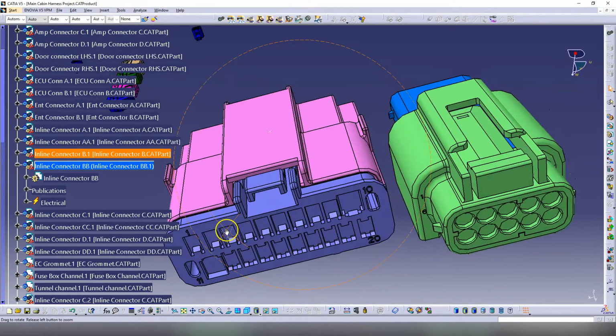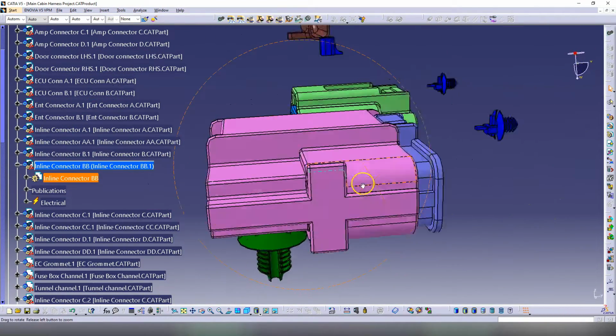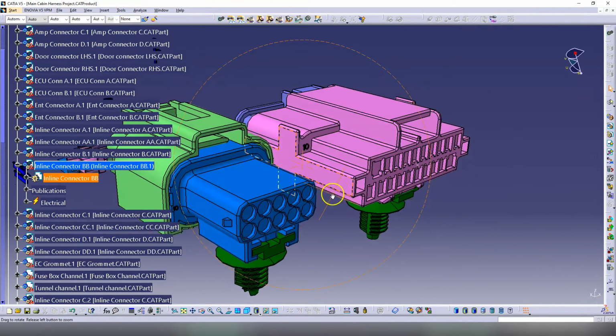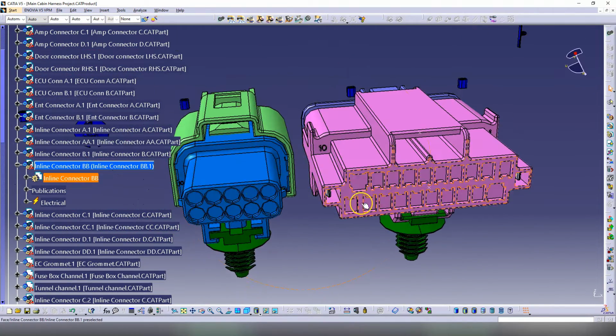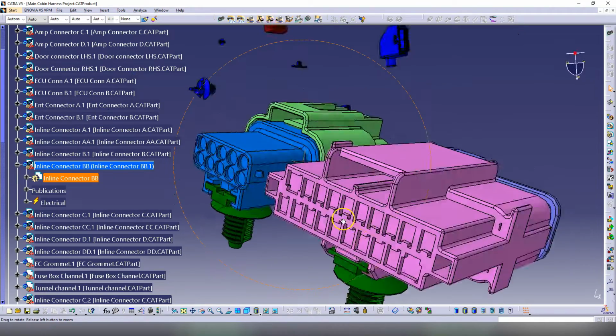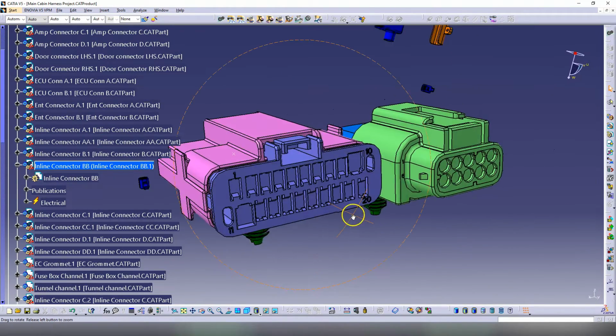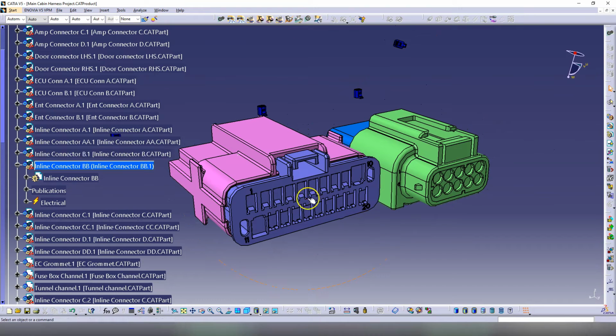And you see those connectors are very detailed. I'm going to show in the course how you download these connectors. Where do you find them? They are free everywhere on suppliers, and I'll show you, if you don't find it and you work in a company, you need to get in touch with the supplier. So I talk about this inside the course. There is no drawing of connectors, so you never have to draw the connectors when you work as a harness design engineer.